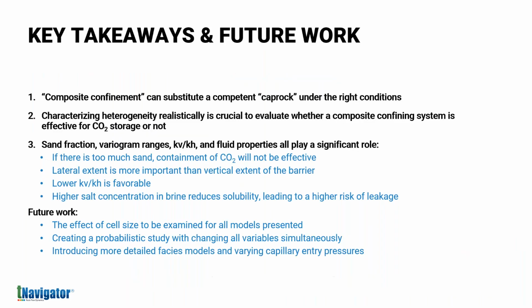So the key takeaways and future work. So first of all, the composite confinement can actually substitute a competent cap rock under the right conditions. And characterizing this is crucial to evaluate whether this is possible or not. So sand fraction, variogram ranges, kVkH, and fluid properties all play a significant role.